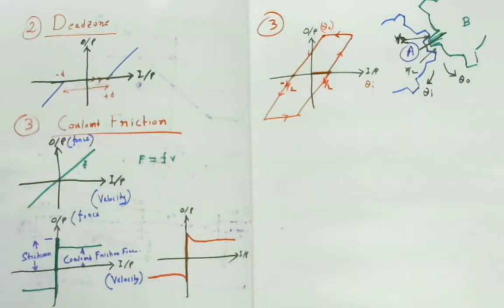Generally gears are fitted after the motor shaft. So if you want to design a control system for the motor, then you have to take care of the backlash nonlinearity. Since the backlash nonlinearity is not a linear system, you have to carefully model the differential equation representation for the motor system, considering the backlash nonlinearity.